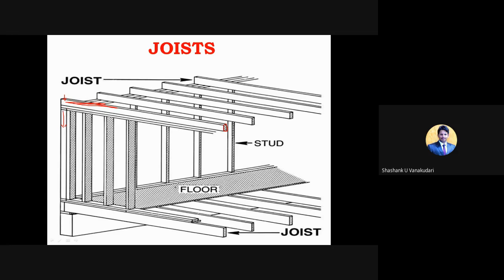So these studs carry both the loads which come from the RC planks as well as the joist, and then rest on the beam or else the floor, depending upon the floor, and transfer that entire load. Here also you can see the joist again, and within this the floor member will come and fix, that is only RC planks.